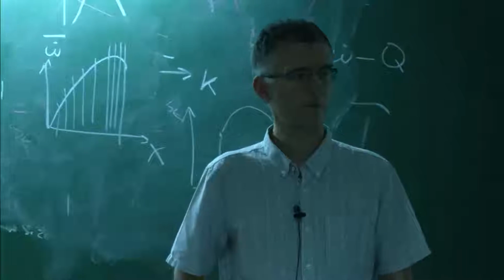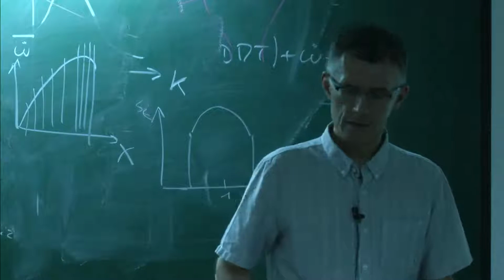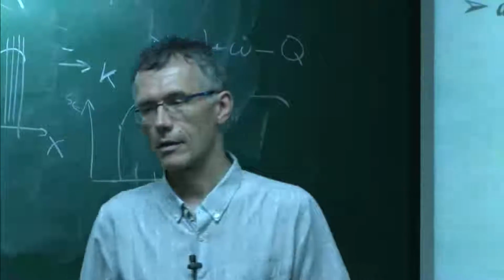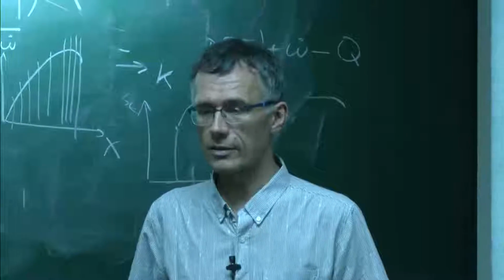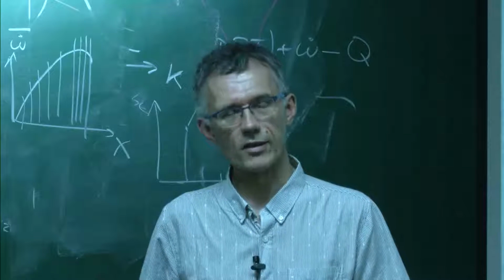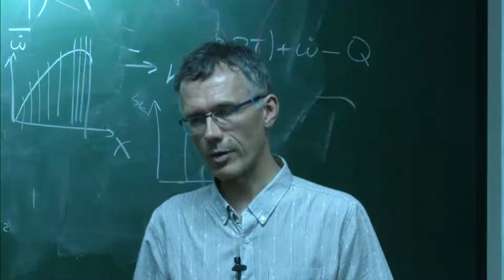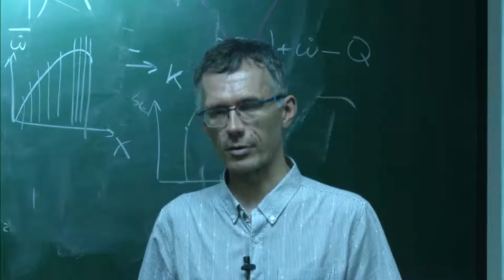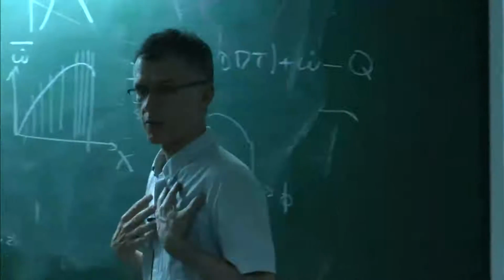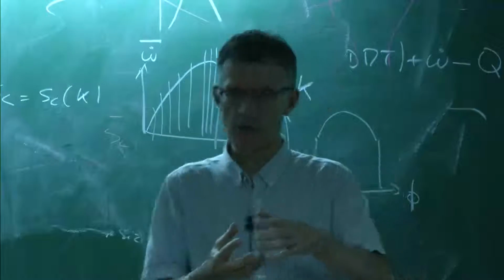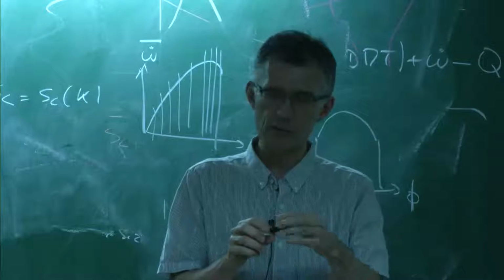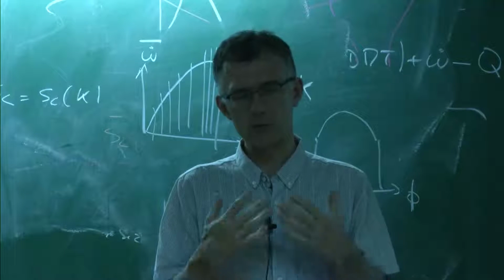Other questions? Do you also talk about the hybrid RANS and LES approach? Hybrid RANS and LES. Oh, you mean DES, methods like this? Not really. We looked at these methods, but they're really for aerodynamic problems. In combustion, DES, for example, is difficult because the geometry of our chambers is very complicated. If you look at a swirler, it would be very difficult to isolate the part which should be RANS from the parts which should be LES. So in practice, we'd rather do LES everywhere.